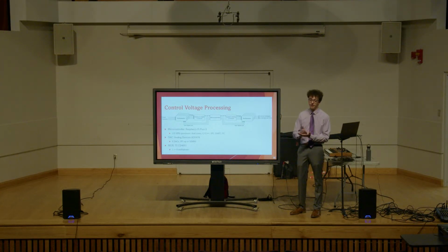So it is in order saying, okay, this control voltage 1, 2, 3, 4, 5, and then that is being sent to multiplexers, which are going to switch those to individual 1, 2, 3, 4, 5 outputs, and hold on to those voltage values so that the analog circuits are getting constant values.